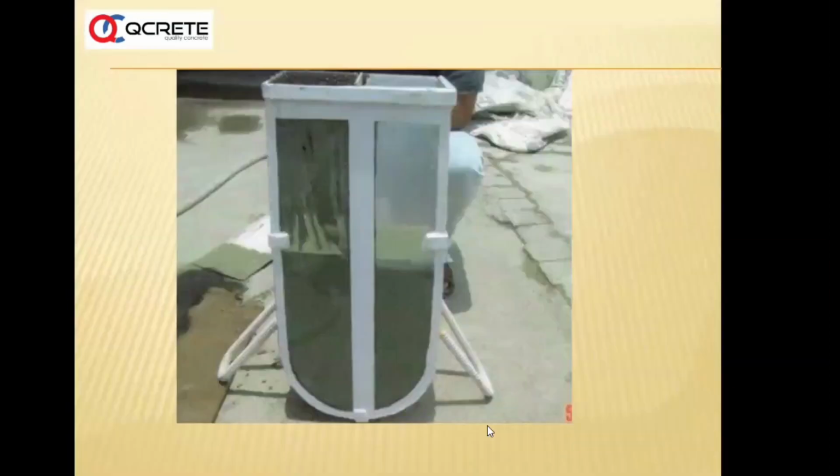There are several tests, because self-compacting concrete is not a simple concrete. It has to exhibit several properties. One of these is the U-tube test, where you fill the concrete here. There is a shutter here. Once you lift the shutter, the level has to be similar, just like water. Both the limbs, limb A and limb B, have to be at the same level. If the difference is more than 30 mm, it is rejectable.